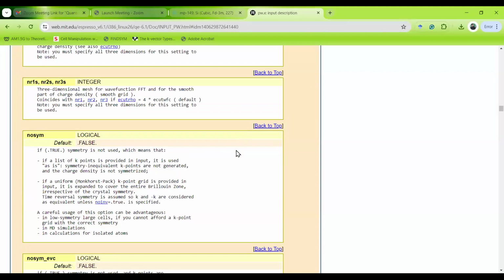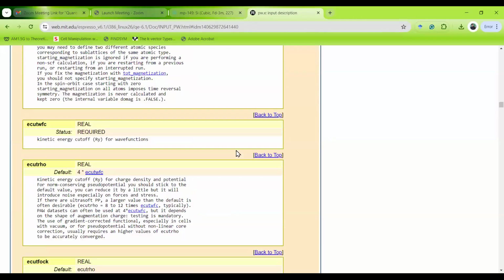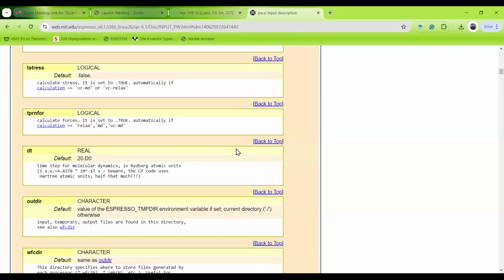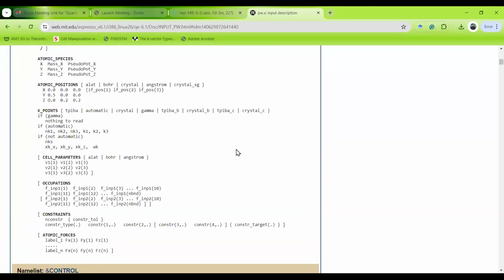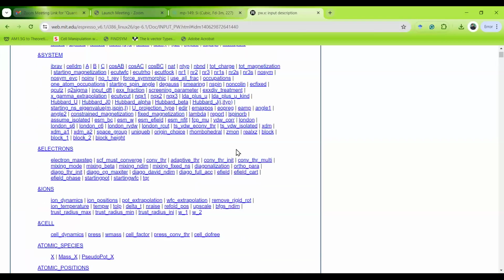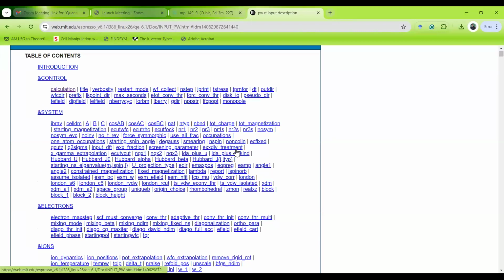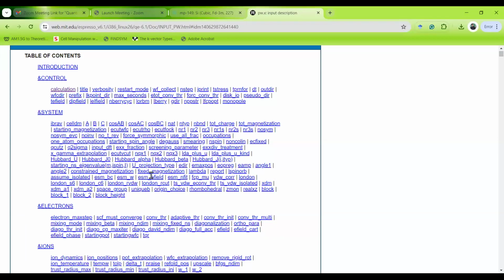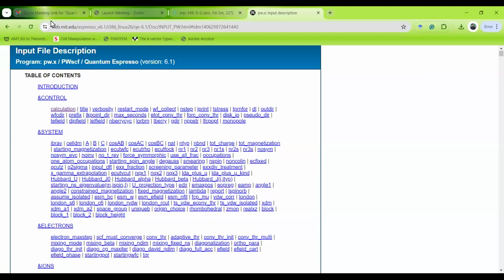Yes, what is the question? You are saying you are applying the Hubbard parameter. Sir, I am using the material WO3, in which I use the Hubbard parameter 6.2. But as I type in 6.2 for W and go to the input file and save it, it disappears and already shows 0.000. So how can we apply Hubbard in Burai? Okay, can you show me, please? Okay, so now you understand how you can find out the significance of these parameters from here. Now I will go to the Burai section.